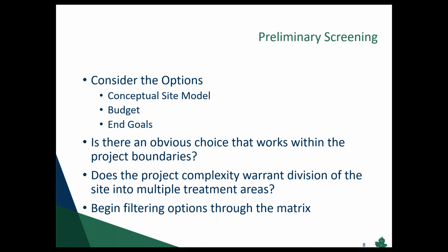So after 2 rounds of persulfate injection, we took a step back and waited for it to play out its course of activity. We did some confirmation sampling, found an even smaller area that needed some additional work, and had planned on it before. So we did an oxygen release substance as a slurry in those limited areas that stimulated the aerobic biological growth to chew the rest of it up and got the site to closure.